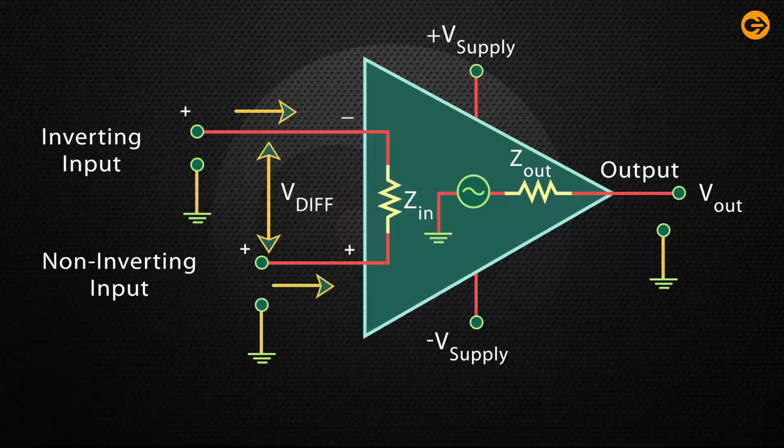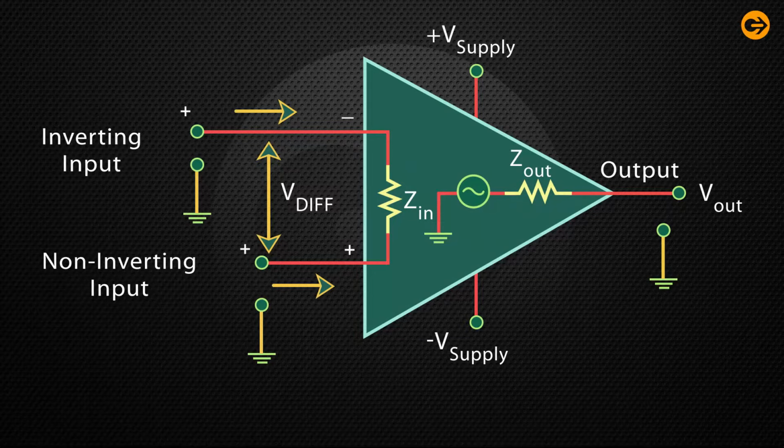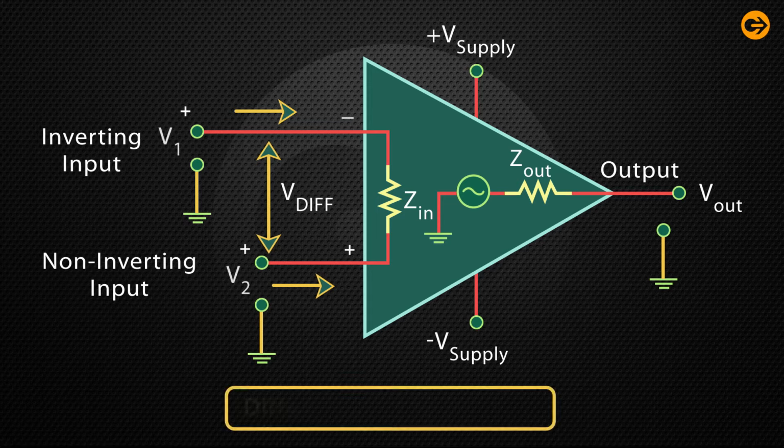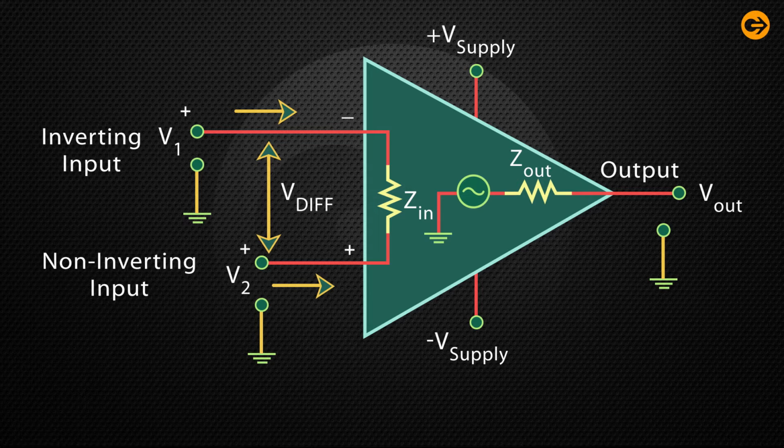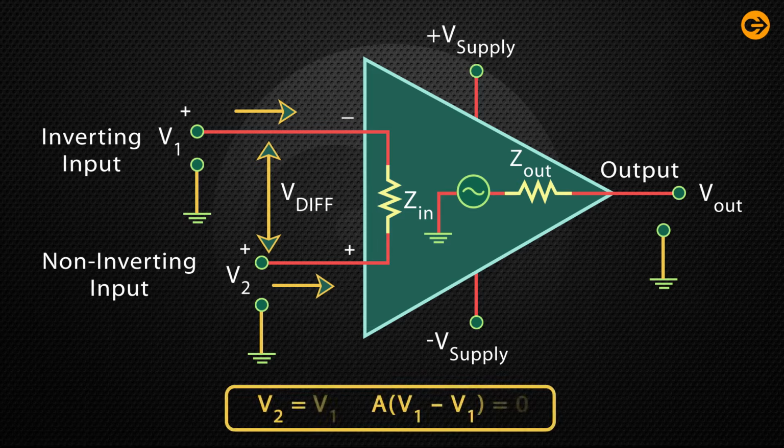An operational amplifier only responds to the difference between the voltages on its two input terminals, known commonly as differential input voltage, and not to their common potential. Then, if the same voltage potential is applied to both terminals, their resultant output will be zero.